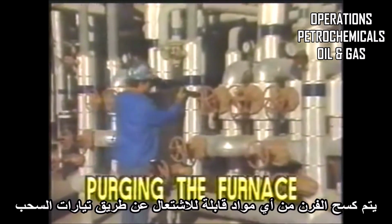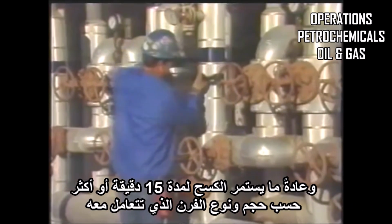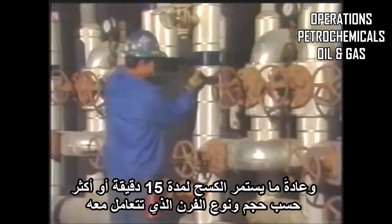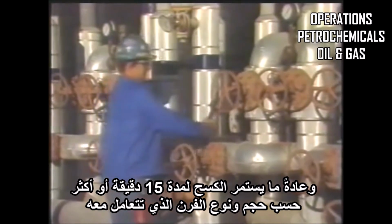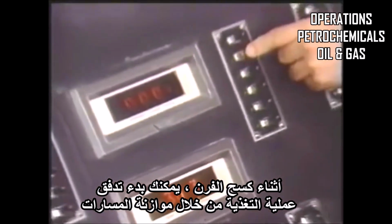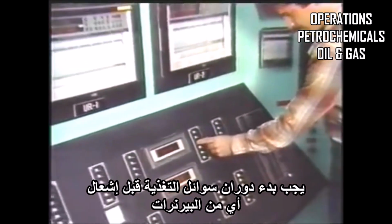Purging clears the furnace of any combustibles and starts a draft. Purging will usually last a minimum of 15 minutes or longer, depending on the size and type of furnace you're dealing with. While the furnace is being purged, you can start the process flow through the coils and balance the passes. This circulation must be established before you light any of the burners.